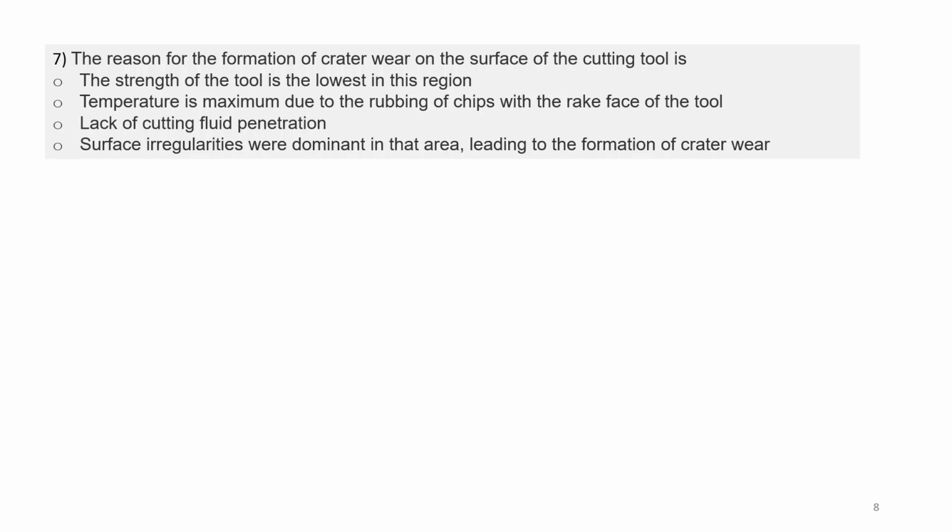Next question: the reason for the formation of crater wear on the surface of the cutting tool is. The options are: the strength of the tool is the lowest in this region; temperature is maximum due to the rubbing of chips with the rake face of the tool; lack of cutting fluid penetration; and surface irregularities were dominant in that area. So the answer will be temperature is maximum due to the rubbing of chips with the rake face of the tool.